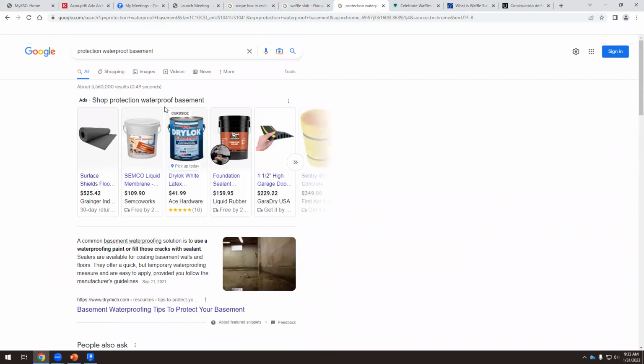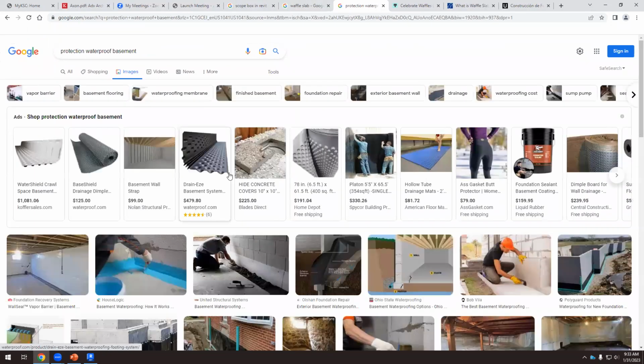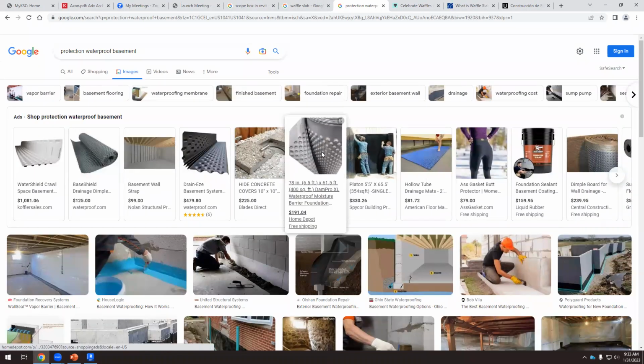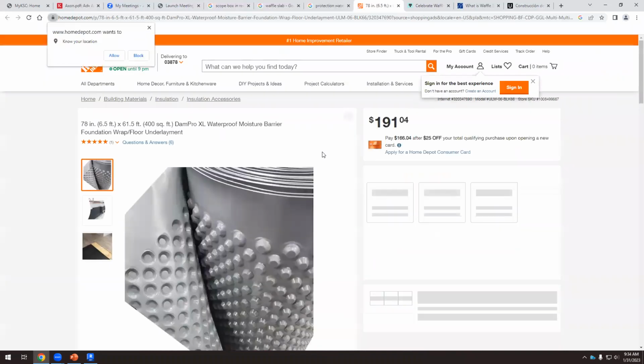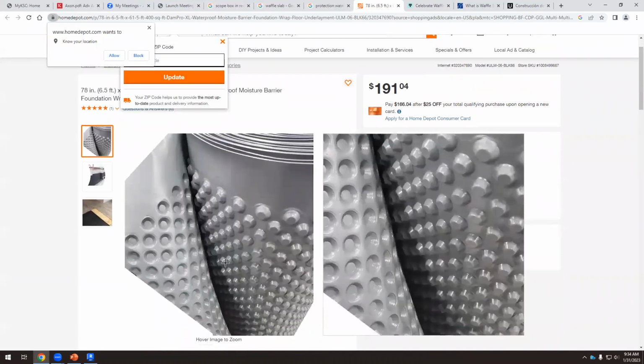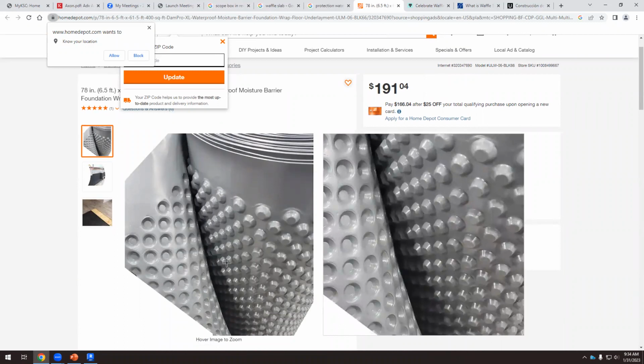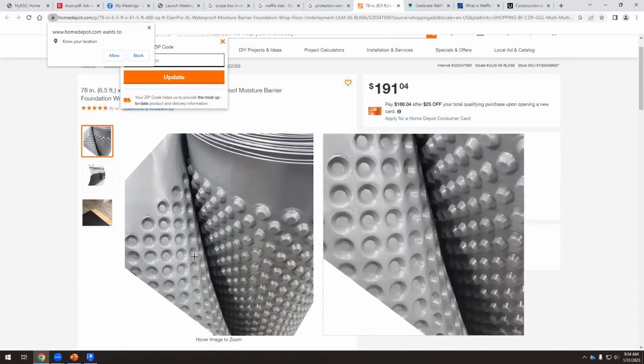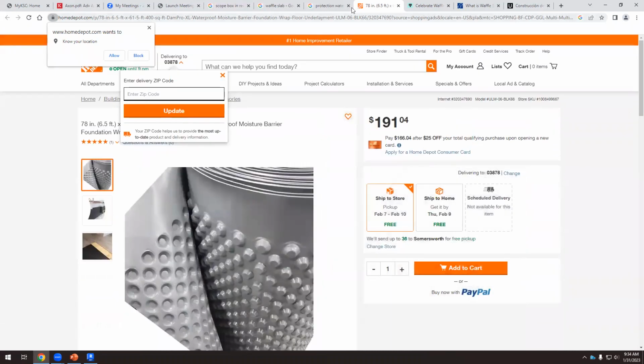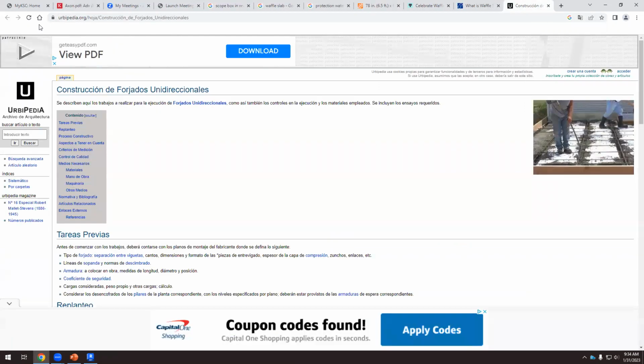a waterproof basement protection. So that is the element. This is like a plastic element. So we put this on the wall. First, we place the painting for waterproofing, or the asphalt. And then we place this because we're going to cast soil on the waterproofing. The waterproofing is something that can be thrown very easily. So that's why we need this plastic protection. Okay. So let me see if we can see one of the details.